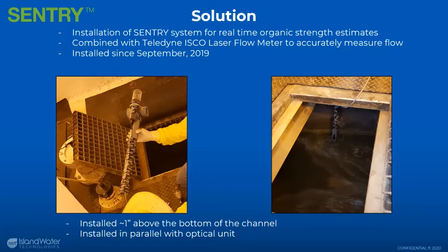So this is a flume. It's a partial flume, 27-inch partial flume. This site has a large diurnal pattern. From the height to the least amount of flow, we can have 8 or 9 inches in difference of water height.